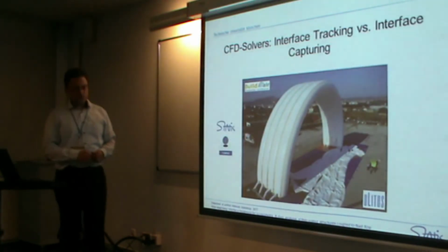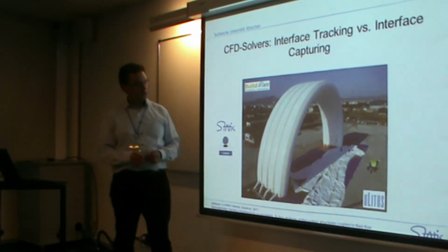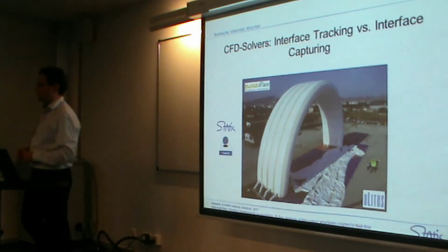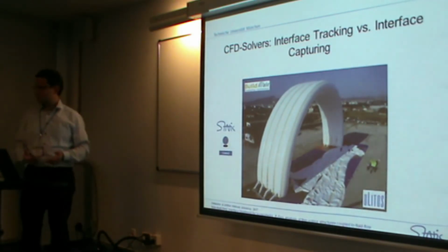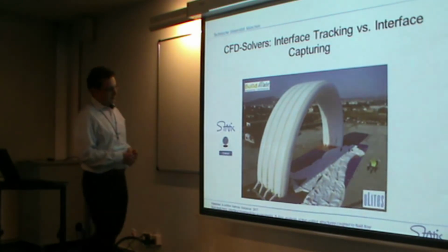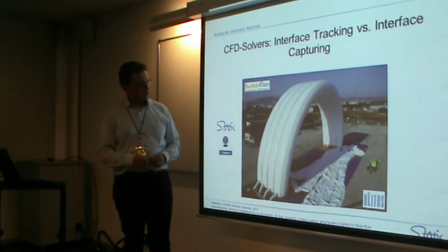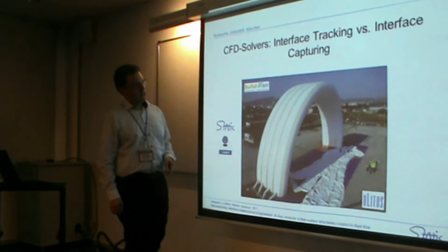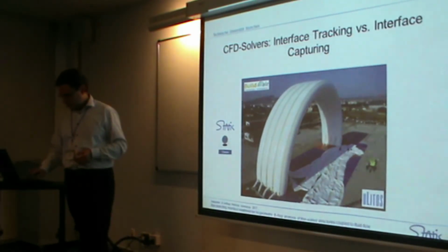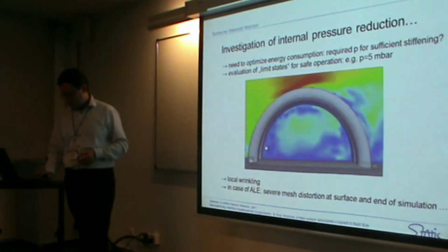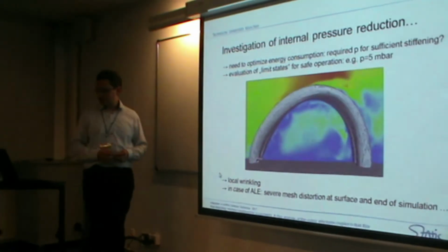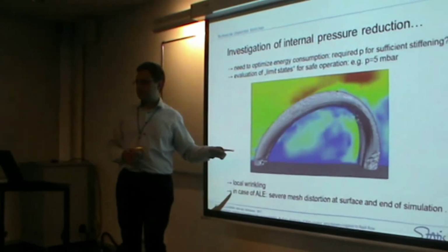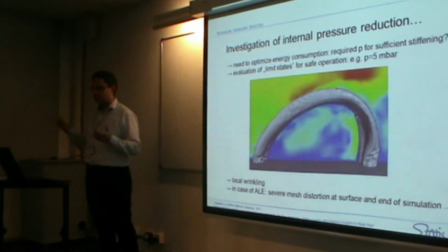Then another point, for fluid structure interaction. Everybody who did FSI already knows that if you have highly distorted interfaces, this is very bad for your simulation because it normally crashes. So if you look at these structures, we also had a collaborative project on these tube structures. This is how they look fully pressurized. That's if they are just in the erection state. And one can imagine if we lower the pressure, that's just a typical task. What is there? Flow comes from the left, a very low pressure, and then this is with a body-fitted mesh, and here OpenFOAM gives up because there is no more convergence, the mesh solver is just crashing.